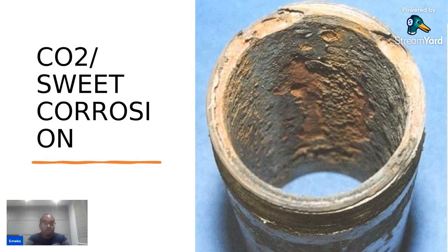Where does this occur? This type of corrosion would happen in internals of vessels, pipelines, and pipework, in systems that contain CO2 where free water is present. It generally affects mainly carbon steel and cast iron steel.